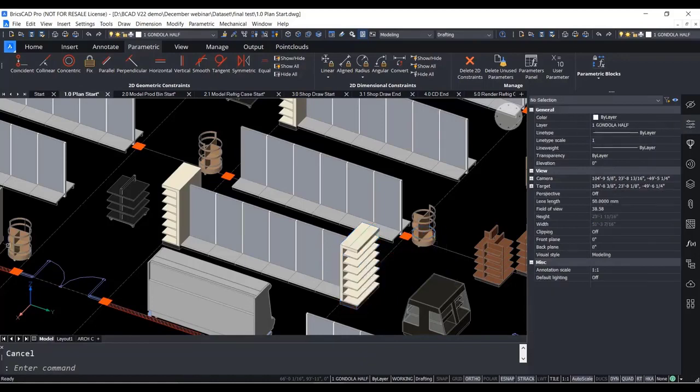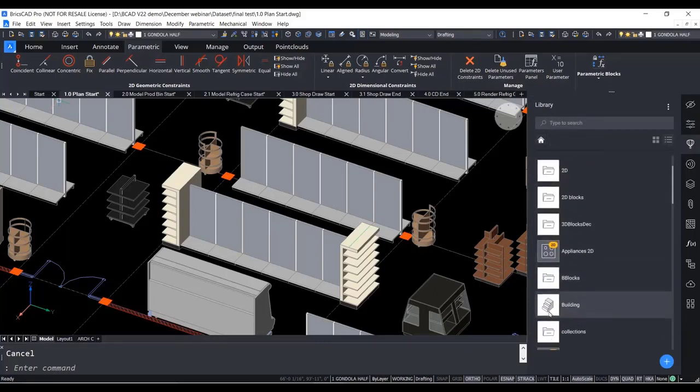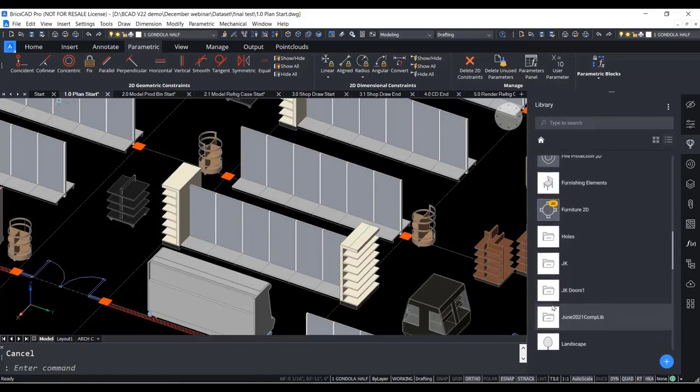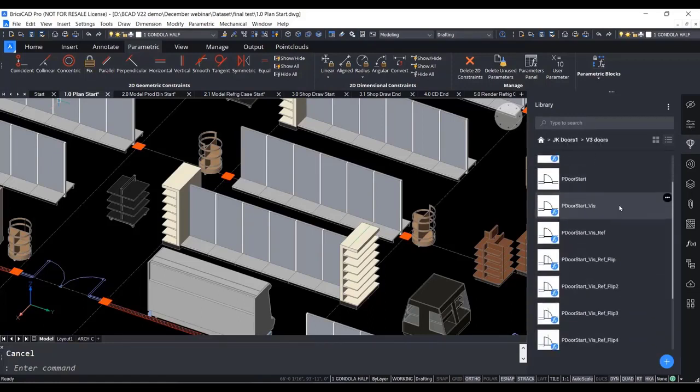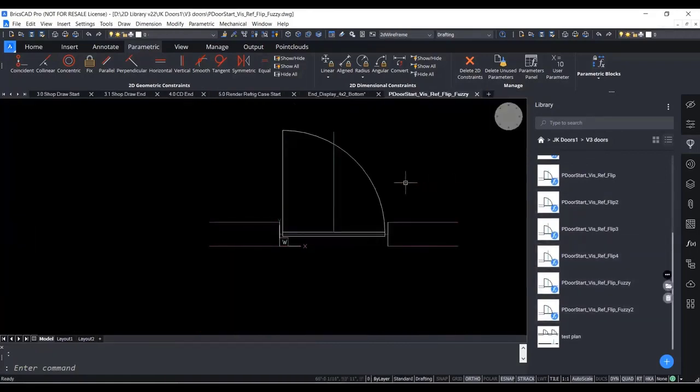In addition to flip line, we've made other enhancements to parametric block functionality, things for visibility states, reference curves, a stretch function, and some others. So let's now look at a door block that uses some of these new parametric features. Because, and this is important, it's now possible to have one parametric block to show the door open or closed, to flip the hinge and/or flip the swing, and best of all, to place that single block in walls with various thickness. So here's our block.